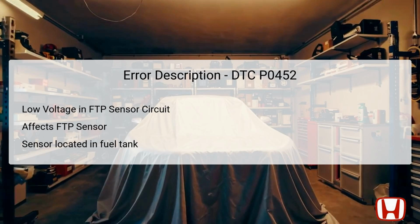The sensor connects directly to the powertrain control module, PCM, which processes the signals it receives. If the voltage from the FTP sensor drops below a specific threshold, typically less than 0.3 volts, the onboard diagnostic system records the DTC P0452.